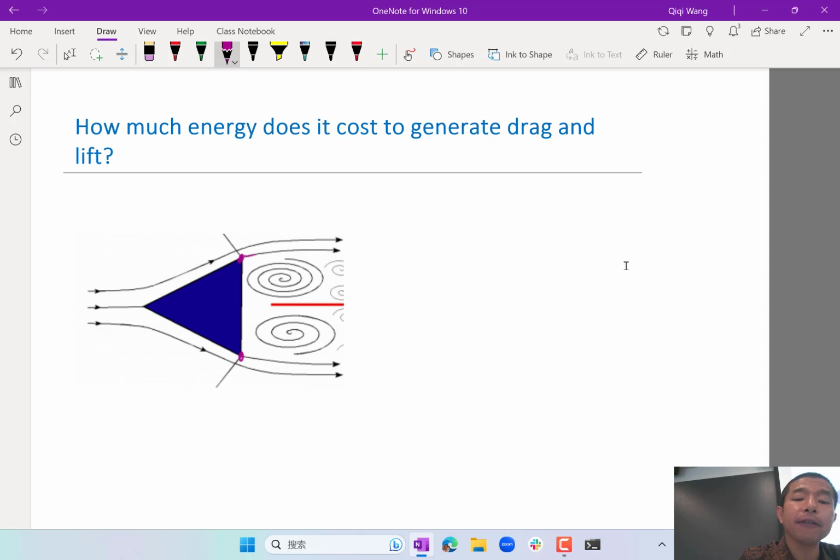Now, in the flow separation zone, there are a lot of random vortices, turbulence, which we'll talk about very late in the semester. But for now, it is sufficient to know that the velocity in the separation zone relative to the solid body is much lower than the free stream velocity. Let's say V infinity is the flow velocity.